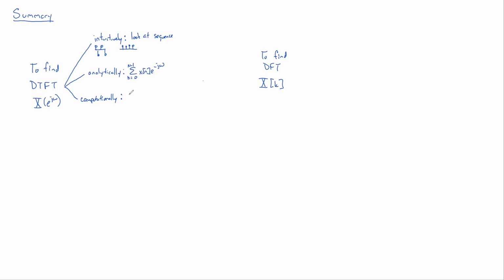So even though the FFT strictly finds the DFT, not the DTFT, if we give it our sequence and we zero pad it big time, in such a way that it's a power of 2, that'll be a good approximation. So here's an example of zero padding it quite a bit.